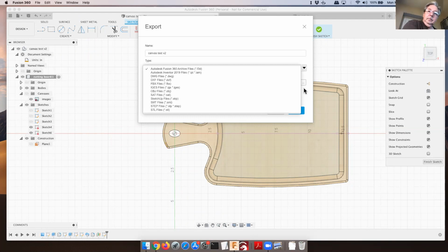Yeah, I'm surprised it doesn't take step files, but we have options. So here's what we can easily export from Fusion 360. Fusion 360 has its own format, which is F3D. Inventor, DWG, the old AutoCAD, DXF, drawing exchange format, also Autodesk. FBX, I don't have familiarity with. IGES is a 3D format, initially surface, but also I believe some solids. OBJ, I think the 3D printer guys are familiar with. It's a little bit like STL, but includes color functionality and stuff like that. Surface texture, yeah.